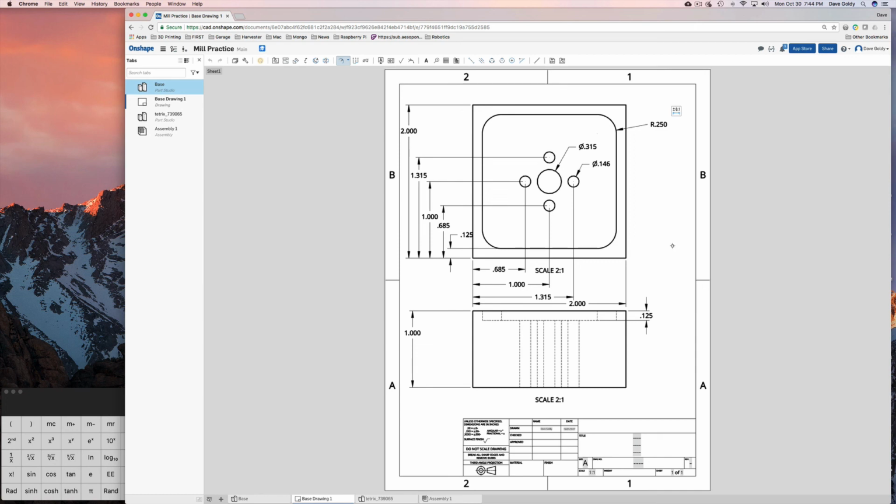You may look at this and say, well, but we didn't identify the radius of this, this, this, this. It's a standard dimensioning practice that when things are typical, meaning all of the arcs are the same here, you only dimension it in one spot. That's the same reason I only dimensioned one of these circles. All of these circles have the same diameter, so I just dimensioned one of them.